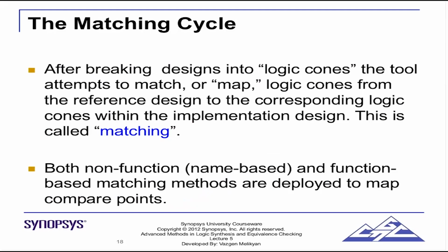Why is this matching required? Let's say synthesis, for example. Synthesis changes names. We have seen that the register names are changed. If you ungroup any module, then the hierarchy will be different, and again the name will be changed. So a lot of design processes, like synthesis or PNR, although PNR usually doesn't change the instance name, will ungroup some hierarchy, or maybe form a separate group. Some of them change the hierarchy of an instance, some of them change the instance name.